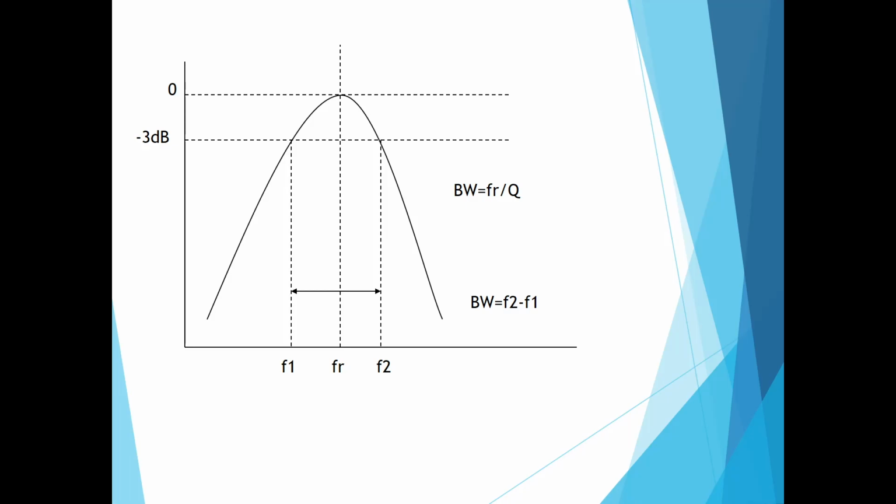If you see from this graph, the bell shape here is the frequency response curve of the filter inside the tuned circuit. You see that the bandwidth of minus 3 dB starts from here. Minus 3 dB crosses at this point and at this point.